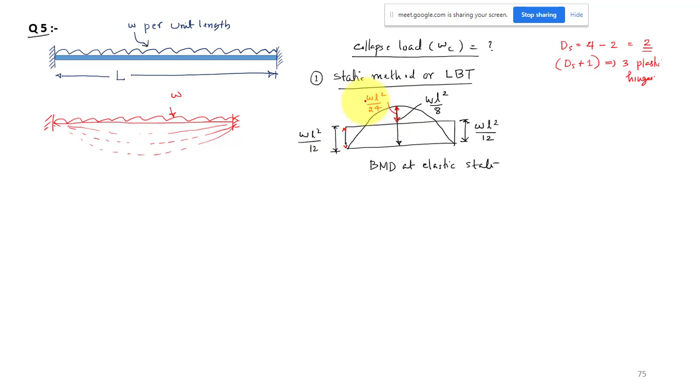And if you are increasing the W, finally the moment at the fixed end will reach the plastic moment first. That section will reach this condition. Your stress will reach the yield condition, because everywhere the moment is increasing, corresponding stress is increasing. Finally, first the plastic hinges will form only at the two supports, because in this case the moment at the fixed end is two times your moment at the midspan.